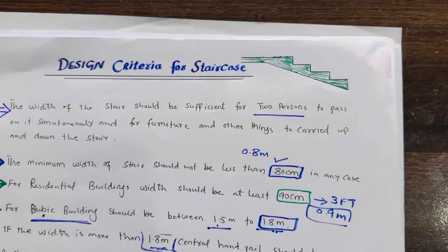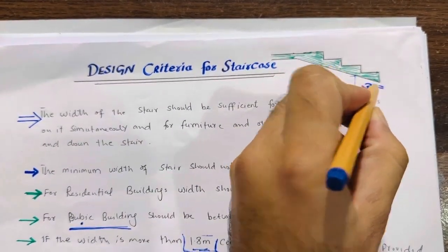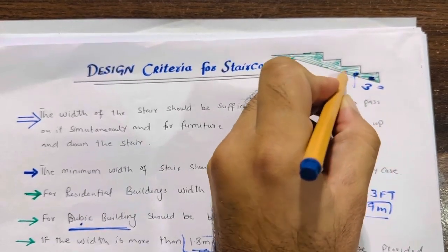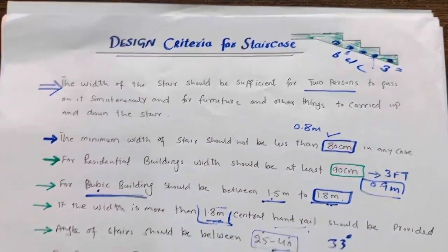And normally, for a structural design, if you are talking about this, the waist should not be less than 3 inches, and next use minimum 12 millimeter diameter steel rod with a spacing of 6 inches center to center.